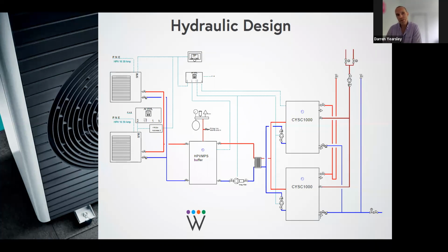What that allows us to do is set a minimum acceptable set point in the storages at 55 degrees. And then the system can sense if the solar system is in production, so if the solar system is producing electricity, we can dynamically change the request in the hot water cylinder up to 70 degrees.